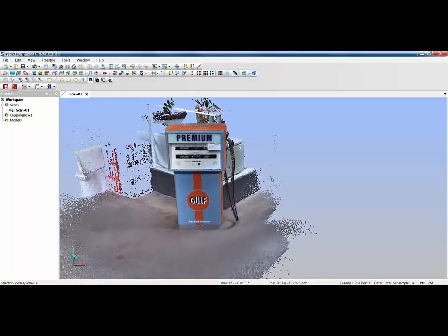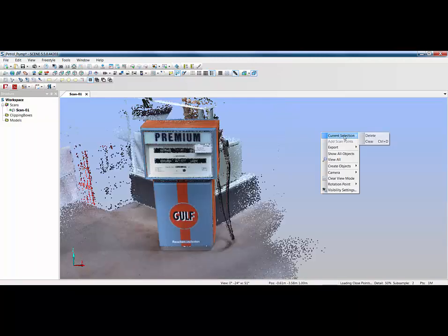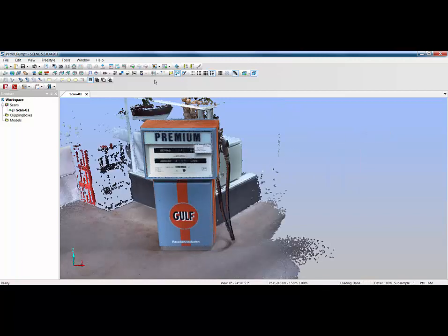Now I can use the clipping box, or because I'm using freestyle data, I've automatically got a scan point cloud. To use the next two tools, if you're using focus data, you'd first need to create either your scan point cloud, which is individual scan point clouds, or you'd need to create your project point cloud, which I've covered in other movies. Once you've done that, you can then use the two tools up here, either the polygon selector for drawing an area around a piece of point cloud, and then right clicking and doing delete,